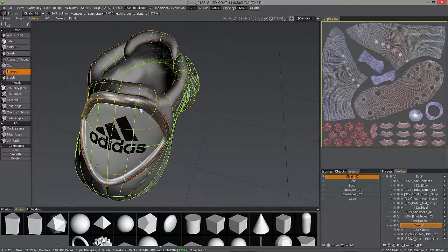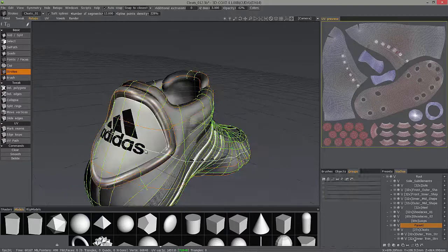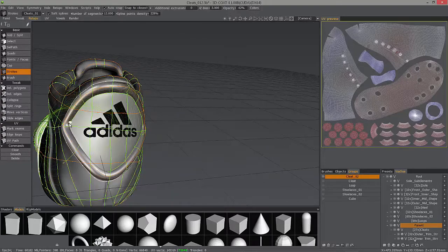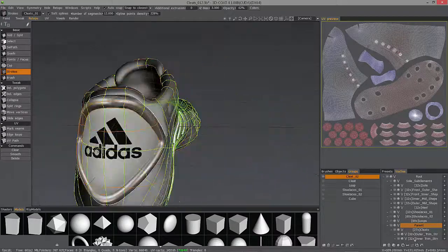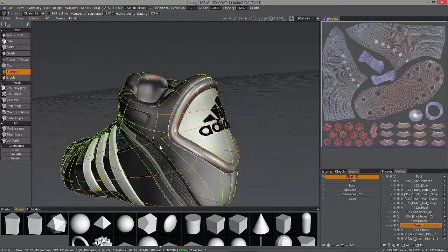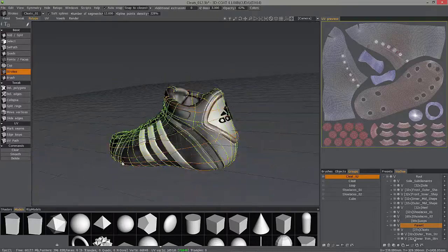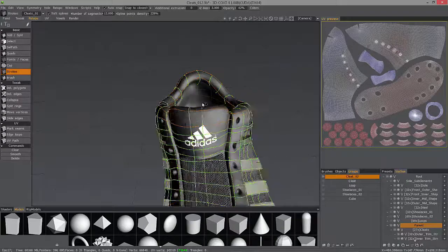When you create these with the strokes tool, you can't always avoid it, but when you create these poles, just keep in mind that you want to go back with the Move Vertices tool and kind of wiggle the vertices until you see a red dot, and it's going to weld them together. I think we're pretty close and ready to go ahead and commit this to geometry.